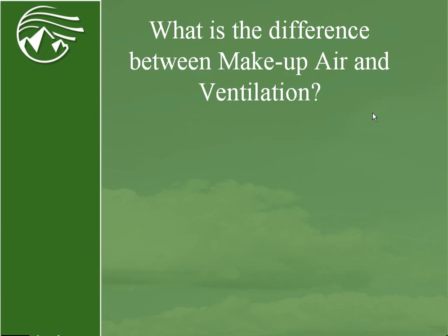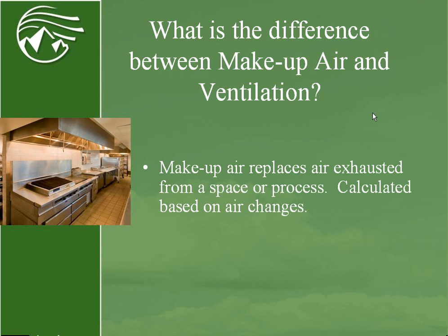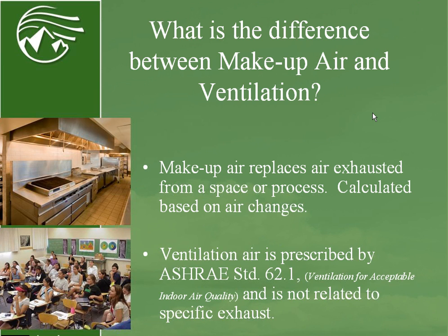But just to go a little farther, what's the difference between makeup air and ventilation air? Because this is the key between the design of the system. Makeup air generally replaces air exhausted from a space due to a process, an application, or positive displacement, things like that. So you're talking about kitchens, industrial applications, anywhere where you have to design based on air changes per hour, bringing in that fresh air to make up the exhausted air.